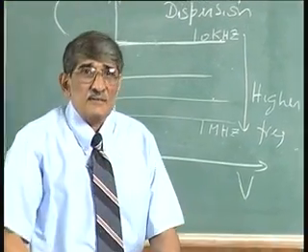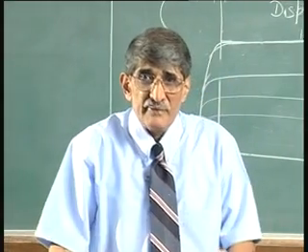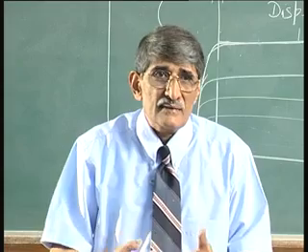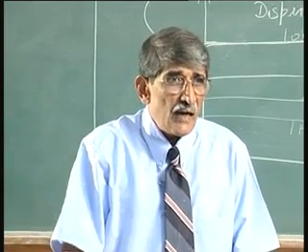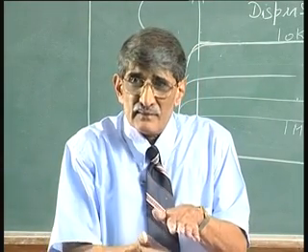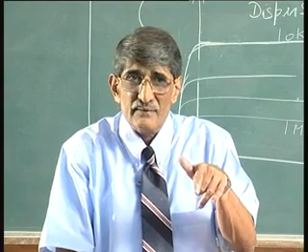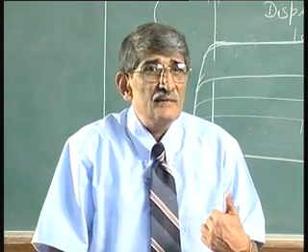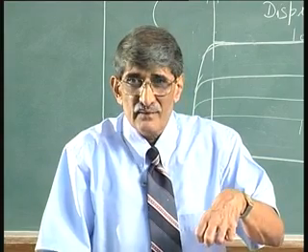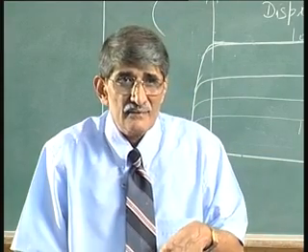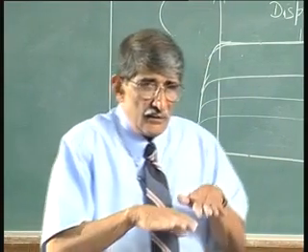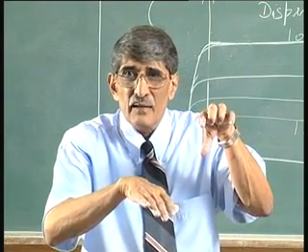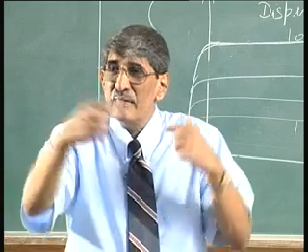When you make a transistor, you end up with poor, low transconductance, because after all it is the substrate which must respond to the applied gate voltage. But now instead of the substrate responding, what is responding is the interface charge. Interface charge is not going to give rise to current. See, when you make a MOSFET, the channel should respond. When you change the gate voltage, if the channel charge responds, the drain current changes.